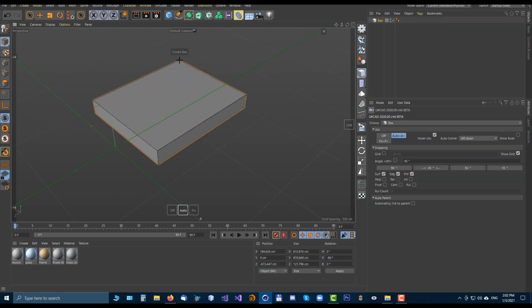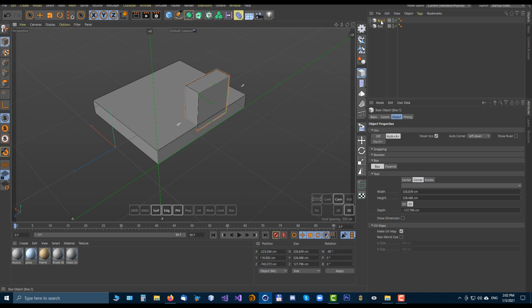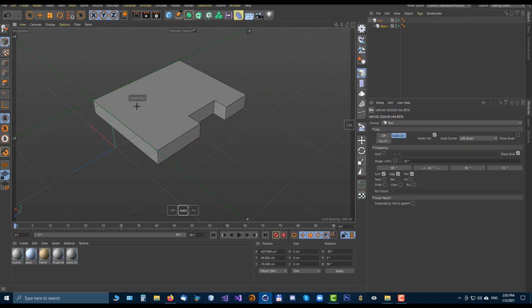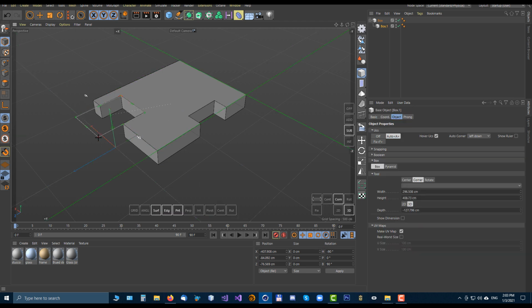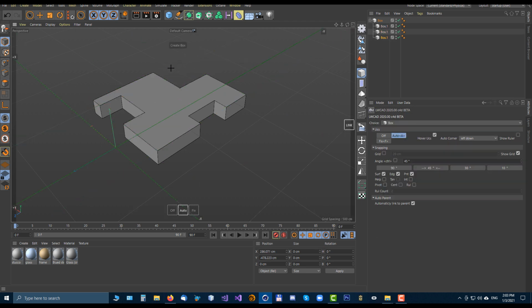When you attach one box to another as a child, then the child object, when Boolean mode is enabled, let's say subtract mode, becomes the parent modifier. In this case, the child doesn't create any geometry, only the parent box is modified by this child object. So the child object is subtracting from the parent. With automatic link, you can drill into the parent this way with child objects.